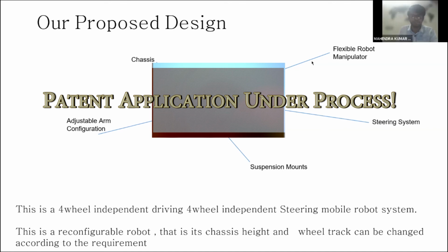Hi, Nayan. Just to add one point here, this particular four-wheel drive is always preferable in a situation where more traction or improved traction is required. As Mahendra has pointed out, during irrigation the field is kind of wet, and slipping is more prominent there. So in that case, if we use caster wheels, there are high chances that we may not be able to steer or control the robot in a desirable fashion. So four-wheel drive is always preferable in such a case. Of course. Yeah, I understand.